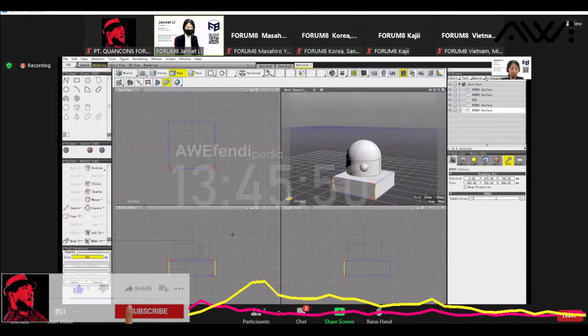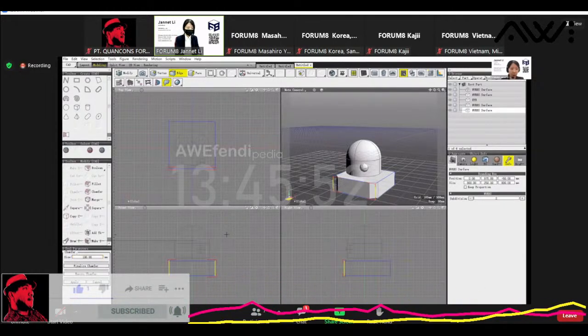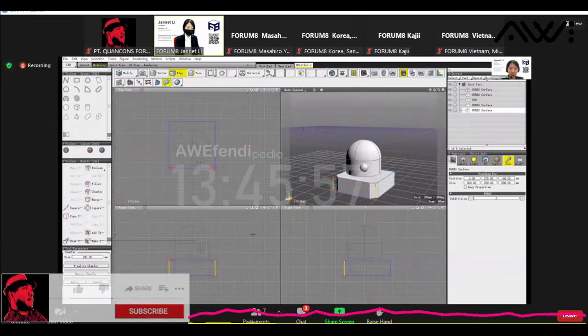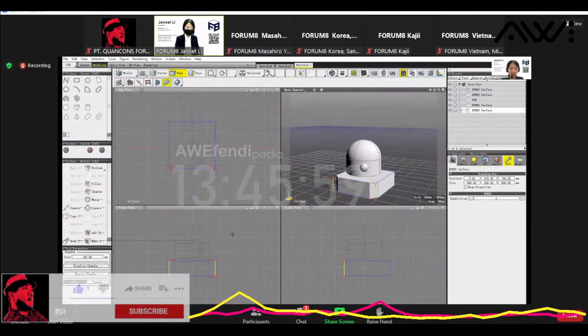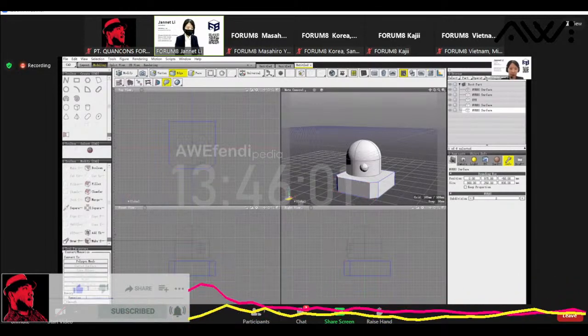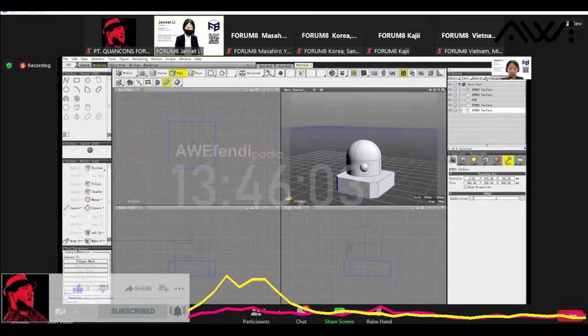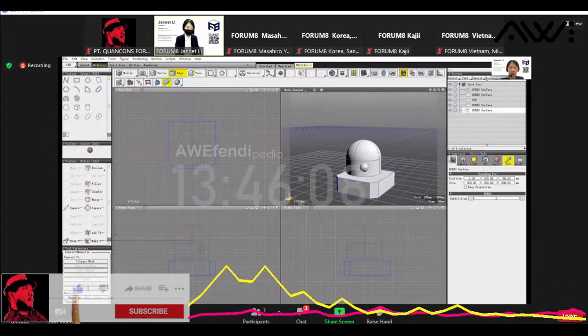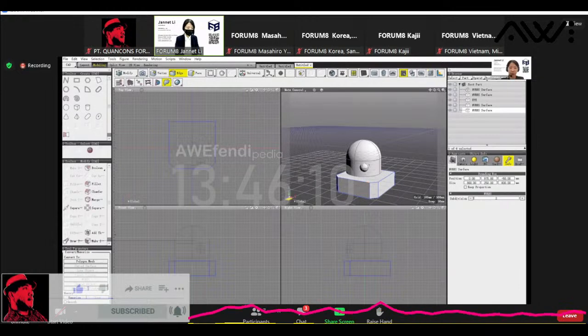Go into the toolbox and pick chamfer, and then please put in 100 in the tool parameters. And you can see that the two edges here have been cut. And we're going to apply that. And the body would be created here.